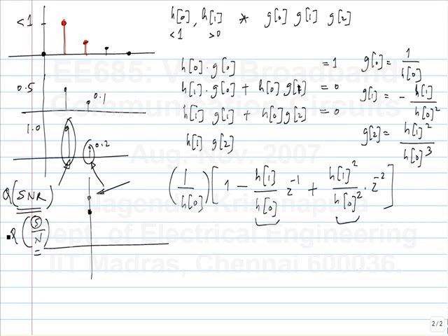You can use either measure. But what I was trying to say was the ratio of H0 to sum of all these square, that is not the SNR. Okay. The SNR is the ratio of this, the received amplitude to the sigma of the noise that is added. That is the SNR that you have to plug into this formula.